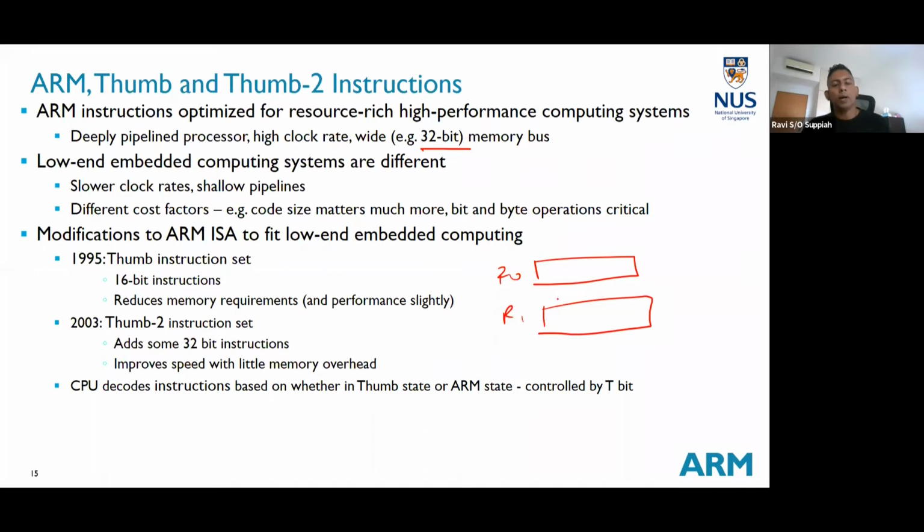Now when your processor is 32-bit, it also makes sense that the memory you interface with is also 32-bit. Why? Then it's easy for you to do a single read and a single write directly in 32 bits. If your memory is 16 bits or some other value, it is still possible, but a lot more work is involved. That means I need to read 2 times, write 2 times, and so on. So if everything is the same, it is easier for interfacing.